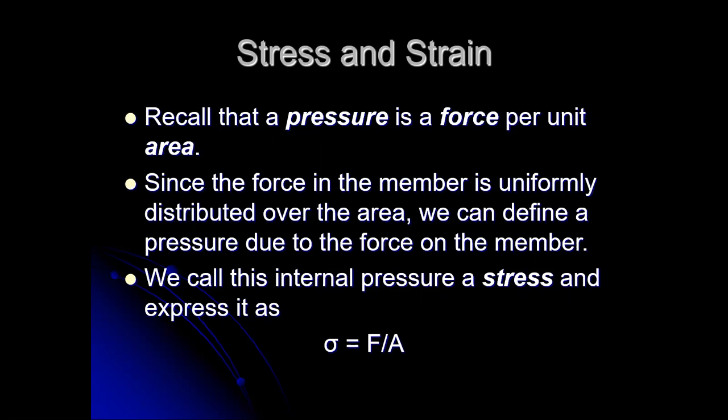If you can find a force, and you can calculate an area, it's not too hard to figure out the normal stress. Now, stress is the internal view of force. It's what the molecules inside the material feel. If we zoomed in so close to the material that we can't see the structure, instead we can just see the atoms and the molecules that make it up, the stress is what we'd physically see.